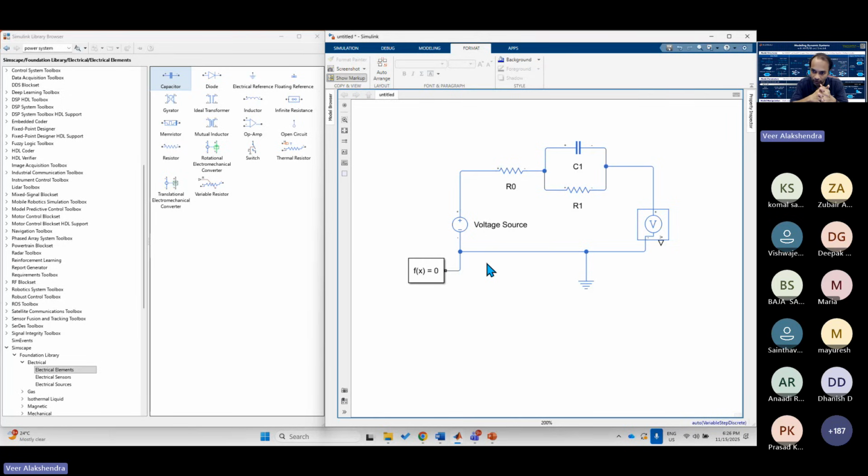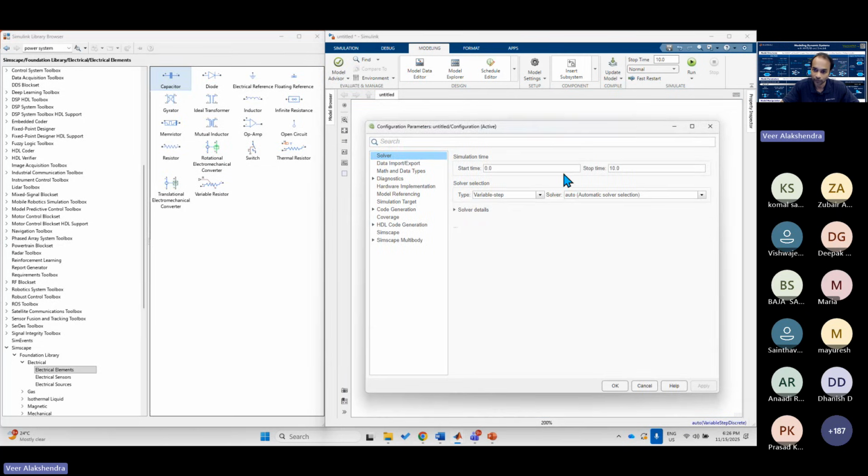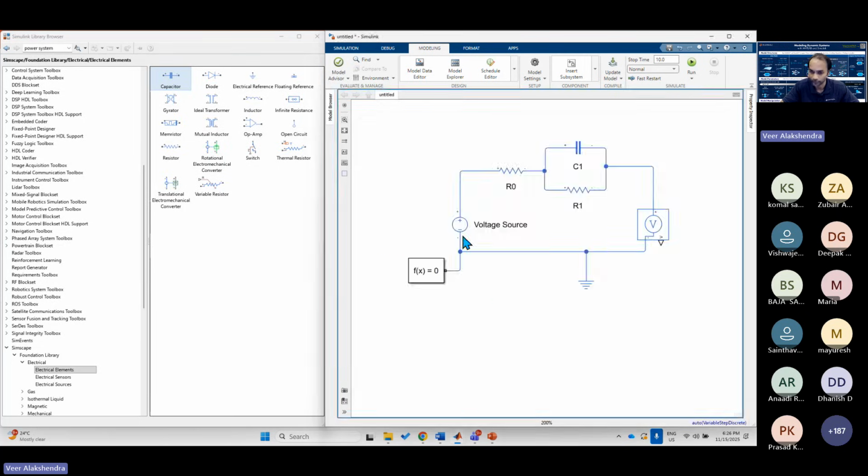Okay. So when you model in Simulink using Simulink blocks, like the blocks that we showed earlier, which were in black and white, those are Simulink blocks. In those cases, you don't need to add that, because the global solver is already taking care of that, which can be found in the model settings. Okay, so you have solver settings for which solver you are using. Then when it comes to Simscape, Simscape will solve for the physical system signals. That's what it is doing. And you can just imagine this as a local solver and a global solver. So this is a local solver.